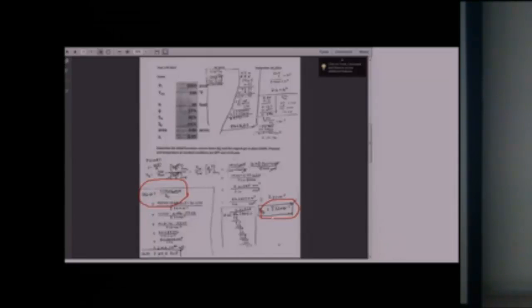And you should be able to know how to convert what we get from a log, the height, the porosity, and the saturation data, with an area, and the fluid property, your formation volume factor, and get your gas that you'd sell in standard cubic feet or 1,000 standard cubic feet in terms of a reservoir volume or a reservoir area. This is your very fundamental reservoir engineering type volumetric equation.